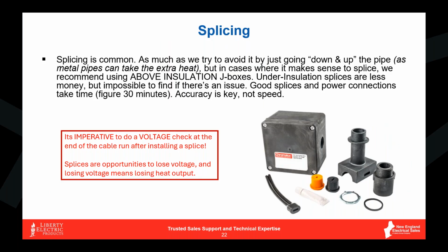These things really have to be delicately pulled apart. You just don't want to lose those bus wires. And you have to try and get as much of that carbon mastic, that molten carbon that's on the bus wires that creates all that great self-regulating action on the cable. We want to strip as much of that off of your actual bus connections as we can. It doesn't have to ultimately be too perfect, but hopefully you can see the bunny ears there in the graphic, those shrink tubing,